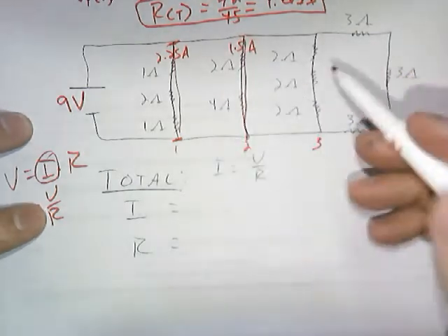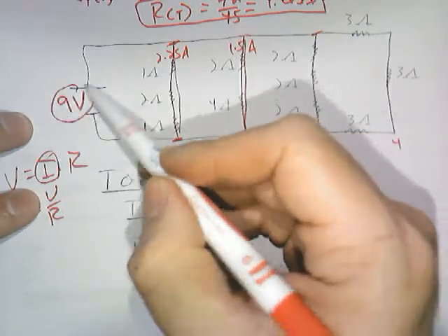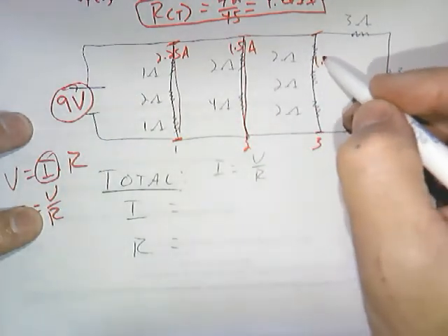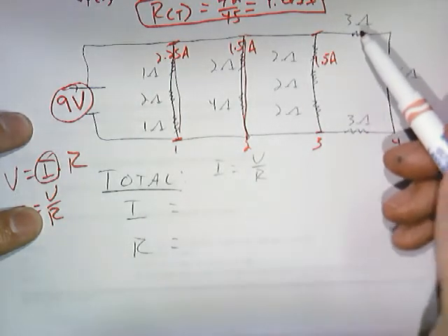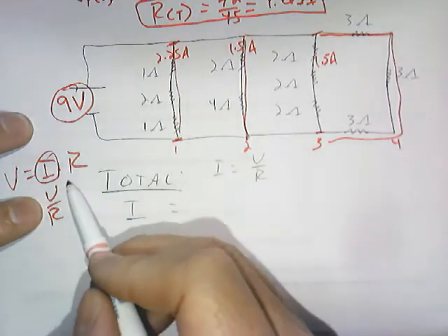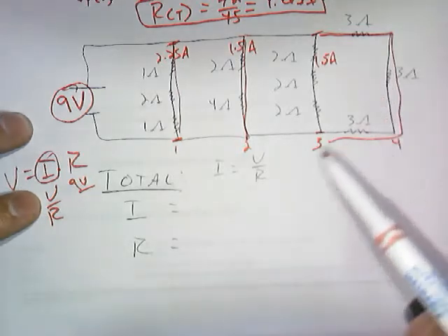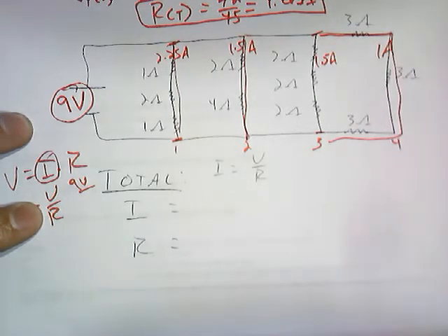Boom. Branch 3 is going to be the same. 9 volts, right? Keep coming back to your 9 volts divided by 6 ohms, is once again 1.5 amps of current. And then lastly, branch 4 is going to be 9 volts, right? Everything's 9 volts divided by, just add up your total equivalent resistance here, 9 ohms, works out very nicely, 1 amp of current.